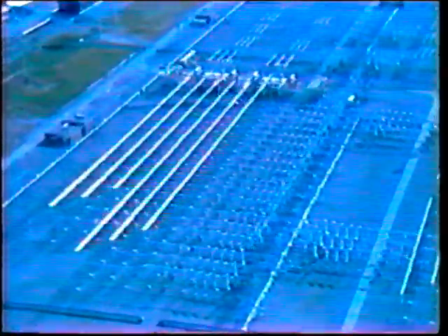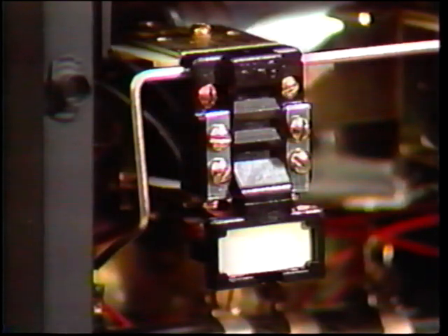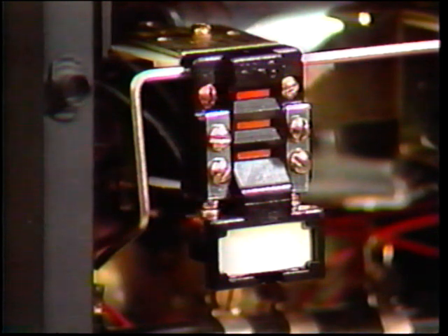Based on the discussion of bus protection, it becomes quite clear that this type of protection does present a few special problems. First, because of its strategic position in the power system, any operation of bus protection relays will clear many circuits and probably cause a major system upset. For this reason, we do not want the bus protection scheme to operate unless there really is a fault on the bus. However, when there is a fault on the bus, it is important that the protection relays operate and clear the bus as soon as possible, preferably at high speed.